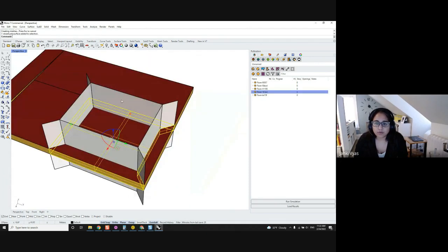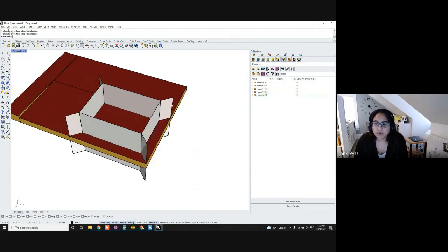It created 1 room here and cut out based on the cutter. Right now we can only support a single poly surface as a cutting surface, so we can't select more than 1 surface. You can see in the room manager that a new room was created. So we'll go ahead and do that for the rest of the space. And now we have a core that we just need to split by the end cutting surfaces. There we go. I think that took care of it.